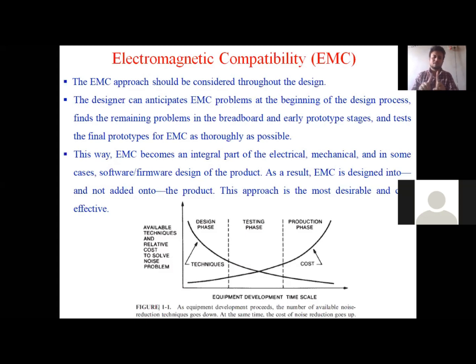So obviously, when current is flowing through one conducting wire, it will produce some magnetic field. That magnetic field may induce into this another conducting wire, and that will give you mutual inductance, which is not desired. That may affect the performance of your device.